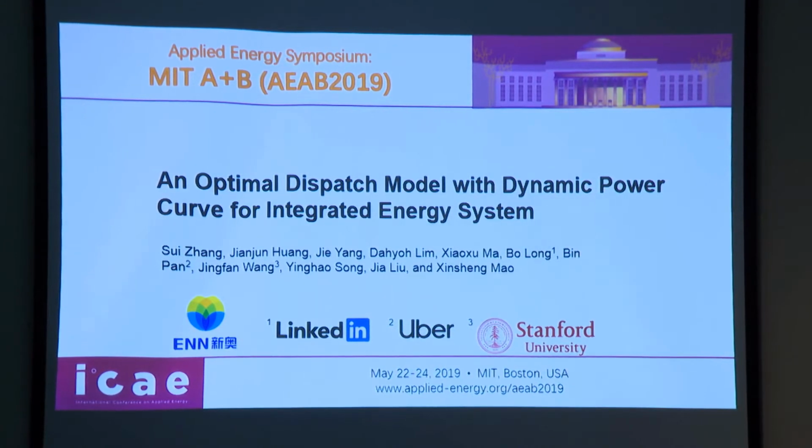And by integrated energy systems, I mean those energy systems where we explicitly take into account the combination of different energy types. It could be at the source, where you could have PV input, electricity from the grid, natural gas. At the device, you could have energy coupling at the devices themselves, like CHPs, combined heating and power, or CCHPs, combined cooling, heating and power. And also at the sink, energy users are using different types of energy. They're not just using electricity. Sometimes they use heat, they use hot steam, depending on their industry. So that's what we're going to talk about now.